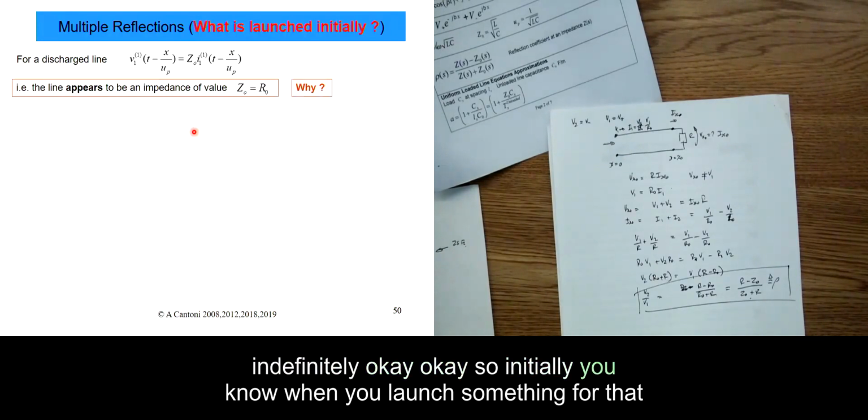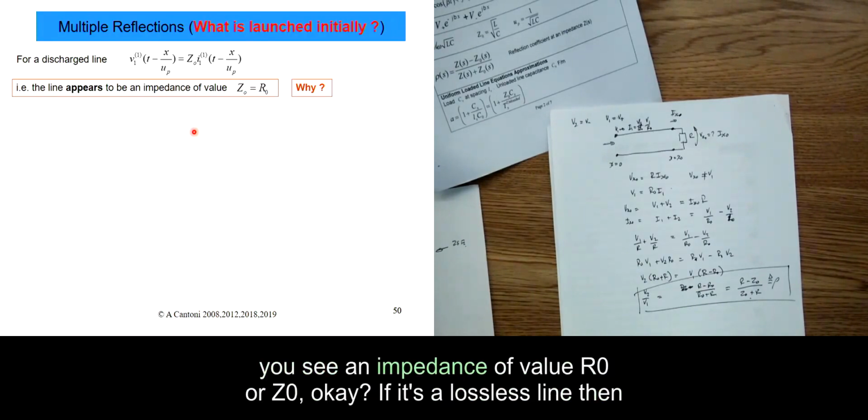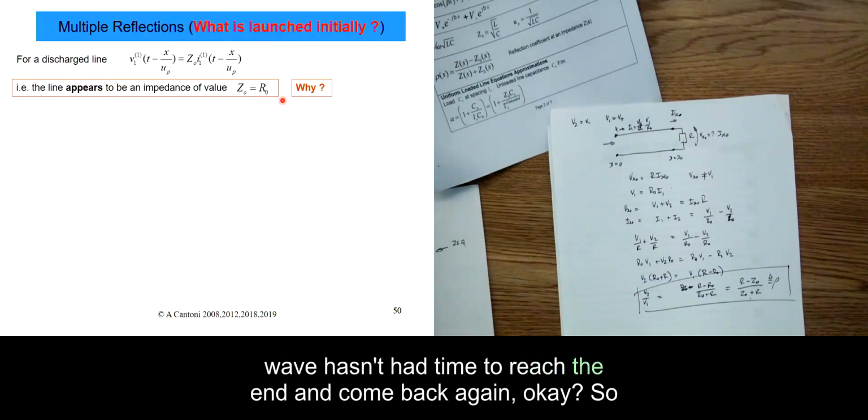So initially, when you launch something, for that instant that you launch it, you would have seen this in the lab. You launch it, you see an impedance of value R naught or Z naught. Okay, if it's a lossless line, then Z naught is purely real, which equals R naught, right? Okay, and why does it just see that for that short time? Why? Anyone? It's because the wave hasn't had time to reach the end and come back again.